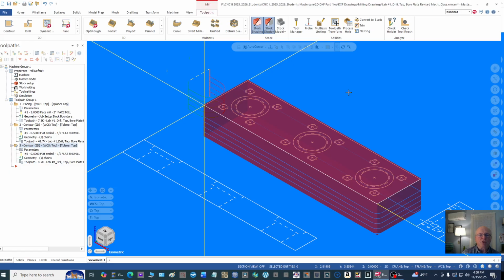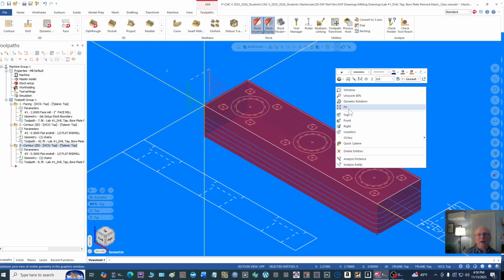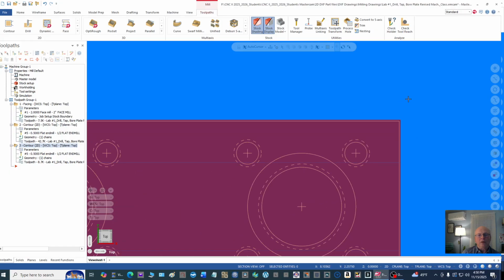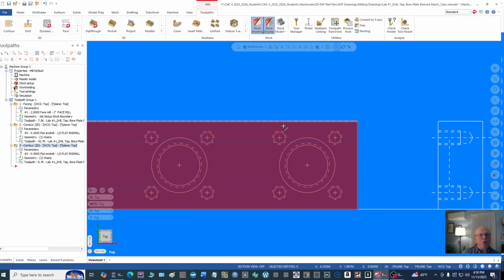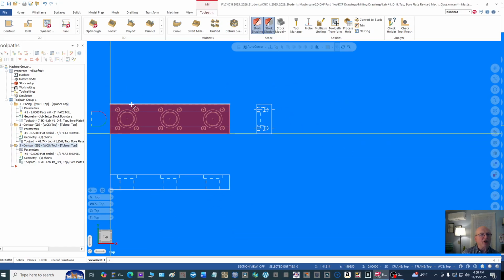And then in the future, we'll show you how to do your spiral milling, where it is helixing in and machining it all the way through. That'll be in a later session. Today, we're going to go ahead and just do the drilling operations and put a pilot hole down through here. So our next operation then is going to be to select our positions here for our drilled and tapped holes. So we're going to have to create some chains.